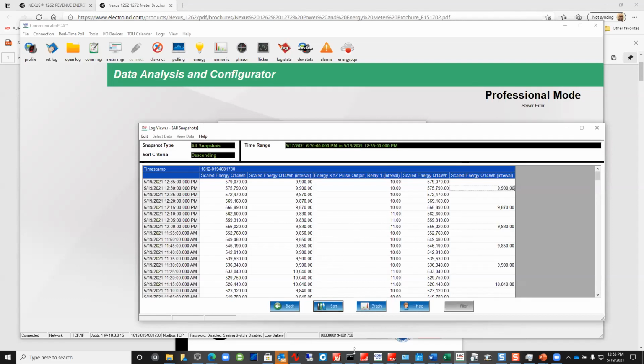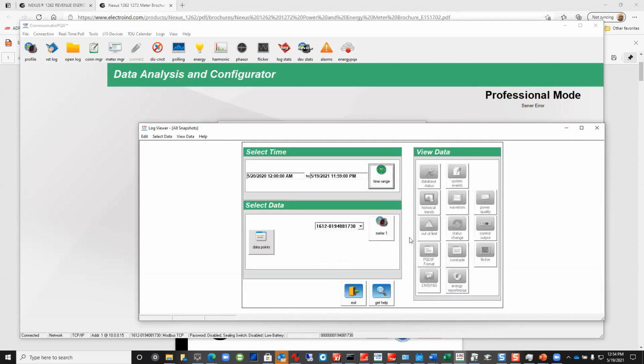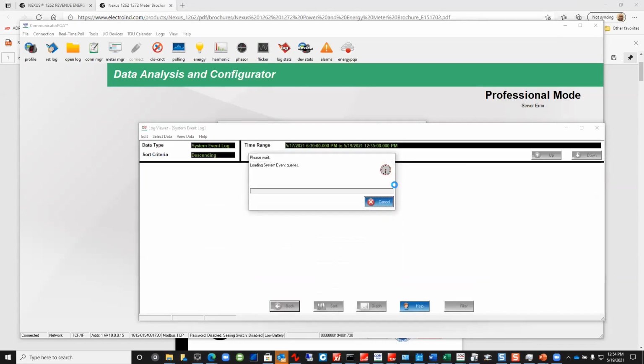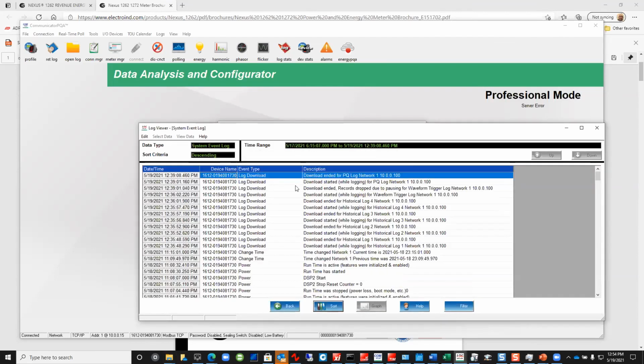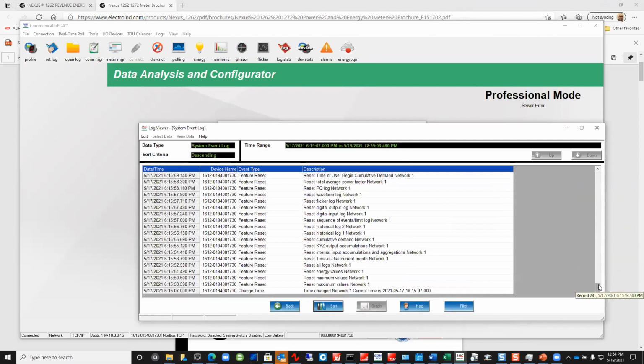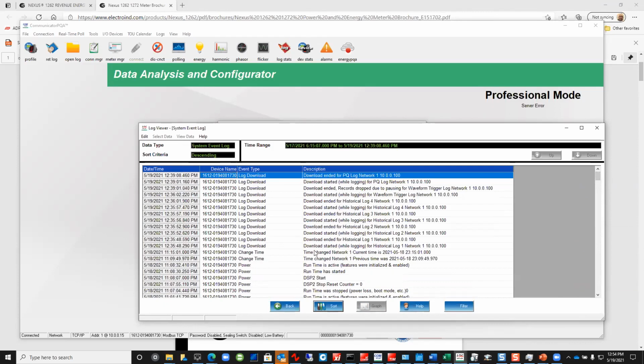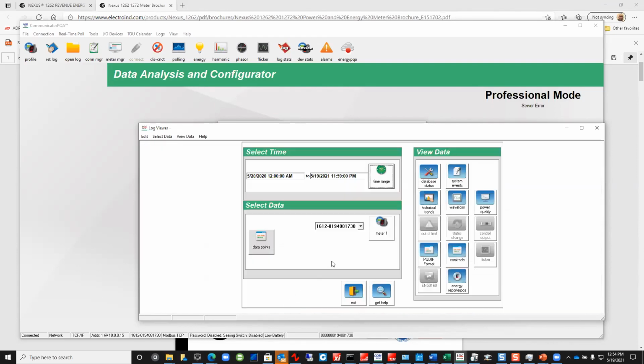And so getting back, these are some of the things, I guess, what we talked about. We could view the power quality, you look at system events, and this is a lot of events here. So every time you access the meter, you make changes. These are all the events that are recorded. Typically, the system doesn't allow you to delete this, and you probably would not want the ability to delete events, for auditing purposes or any other. These are the options that Trent talked about: keep PQDIF format or ComTrade, and that's basically it.